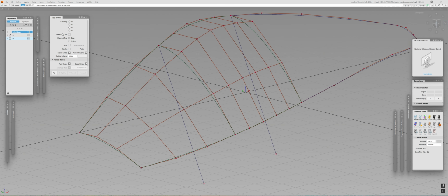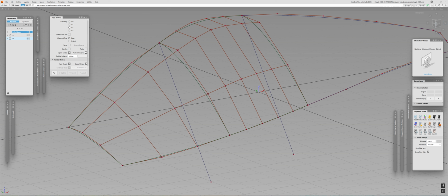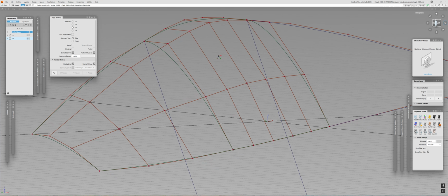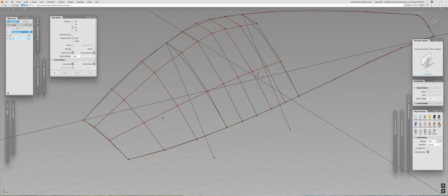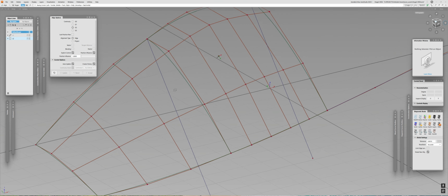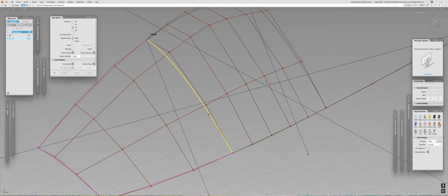So first of all, let's go for alignment. My position influence slider is set to 1. That means that Alias takes the full control over position of the CVs, and it will try to make them collinear as well as it really can, instead of trying to keep the positions of the CVs at their current state, or once again as much as it can. So let me align.